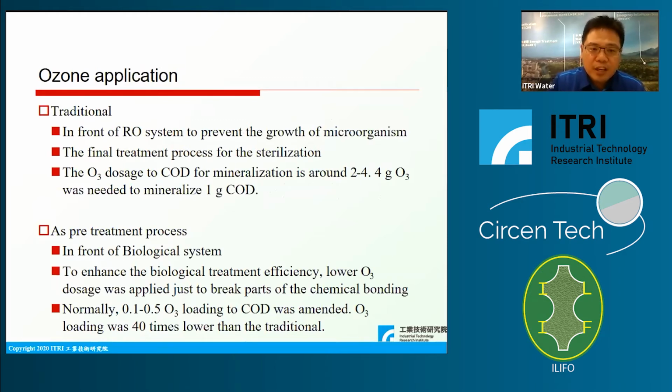From the quantification, the ozone dosage to COD for the mineralization of COD is around 2 to 4 times. It indicates that 4 grams of ozone was needed to mineralize 1 gram of COD. It costs a huge amount of ozone.